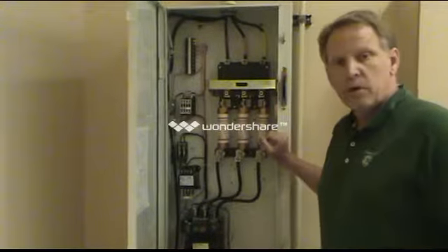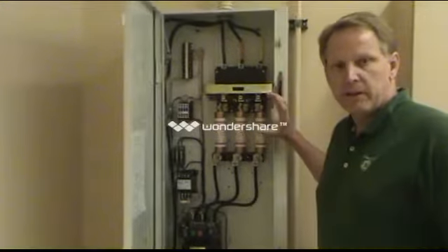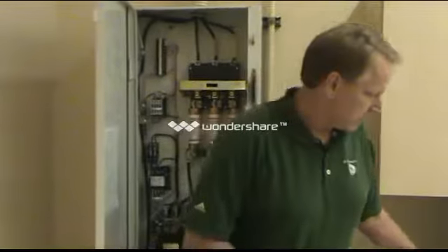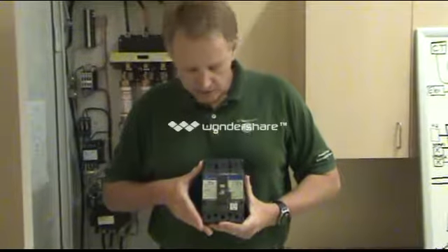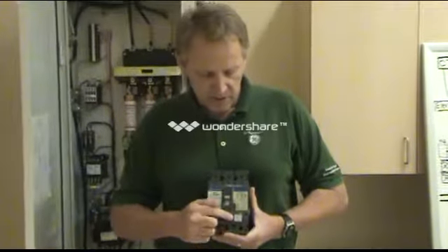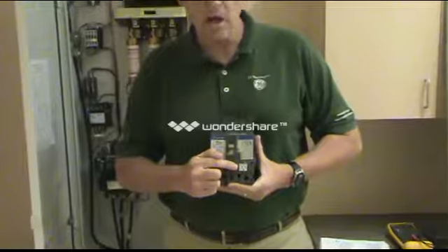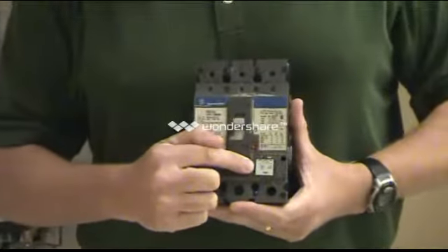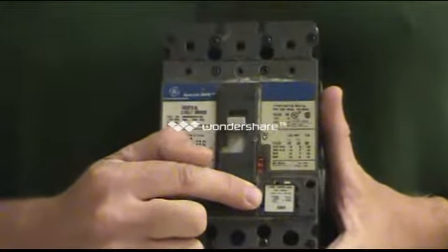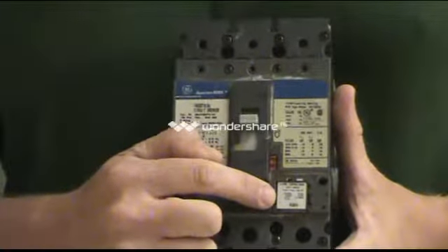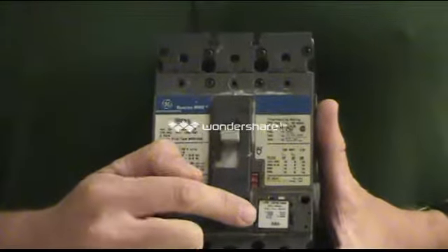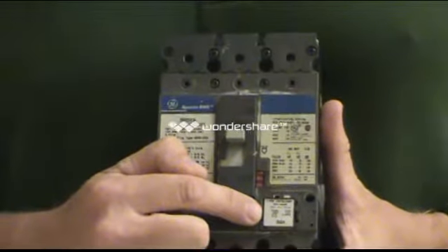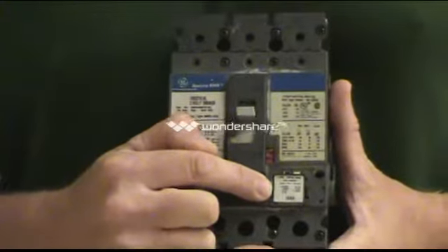Typically, on all newer A1 panels, we're going to have a circuit breaker in there that has modules that can be replaced. So I brought one in. This is a 200 amp frame, but as you can see right down here, this little module can be replaced. So for a VCT it could be 125 amps, for an X-ray system it could be 70. In this example right here, it's an 80 amp module. So the correct answer to put down would be 80 amps. That's what's going to trip to protect our circuits and our conductors. All right, let's move on.